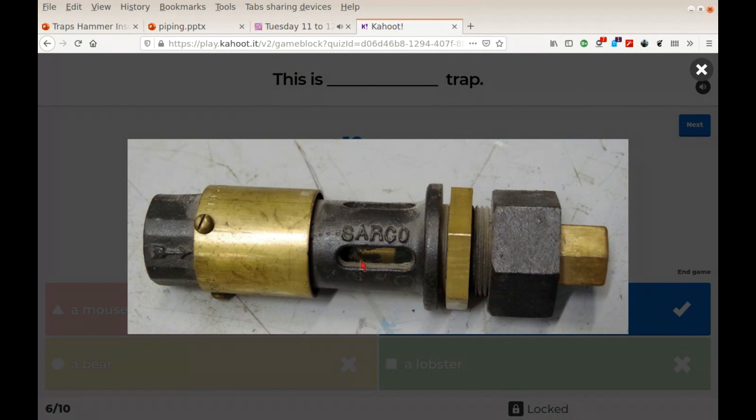So there's a thermostatic element in there, and it kind of works like a thermostatic trap. But at this end here, where there's that kind of like a nut, you can actually adjust the condensate discharge temperature. So you can discharge relatively low temperature condensate at 60 degrees. You can discharge condensate that's 100 degrees. And it has certain applications and advantages, but also has certain disadvantages.